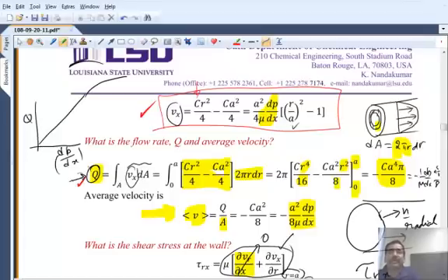It comes from external disturbances. If there are the slightest disturbances externally, the unstable modes in the flow will grow, and then it will develop the v_r component and the v_theta component. But if the Reynolds number is low, those disturbances will be killed, because viscosity is a damping mechanism. So Reynolds number is a competition between inertial force and viscous force. If Reynolds number is high, inertia is high. When inertia is high, these velocities play havoc. They play their own game. But if the Reynolds number is small, viscosity is large. So any perturbation that you introduce will be damped out by viscosity.